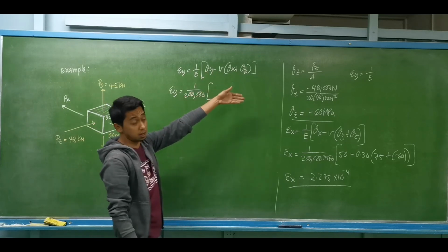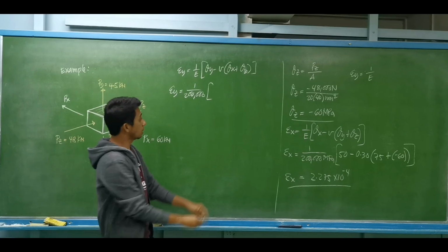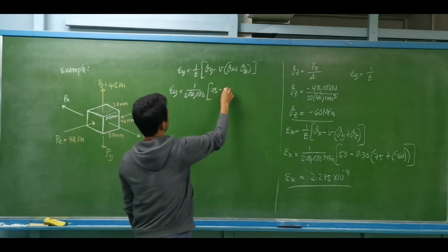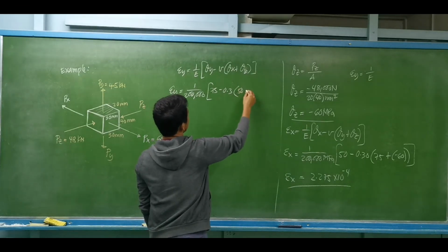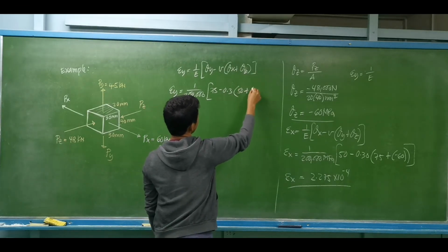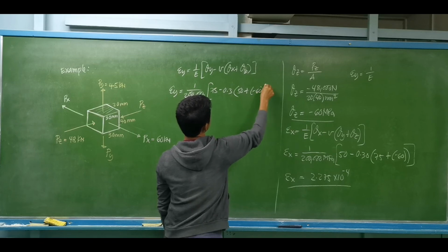The stress along the y-axis is 75 megapascals minus 0.3 of the stress along x, which is 50, plus the stress along z, which is negative 60.